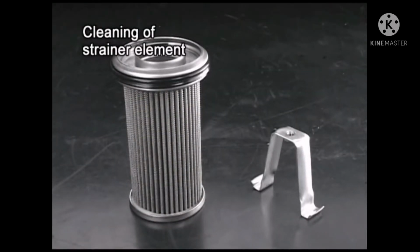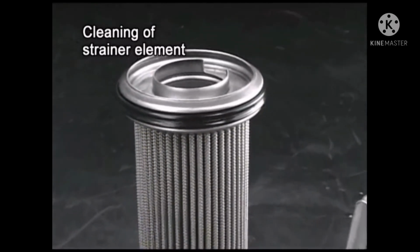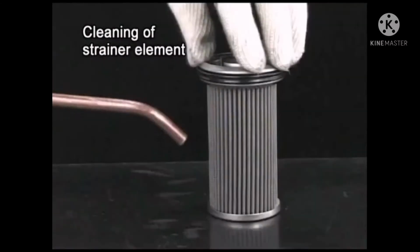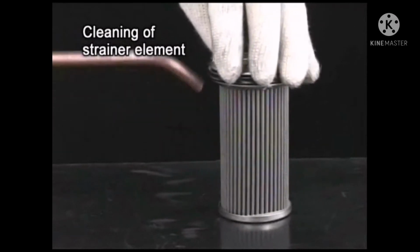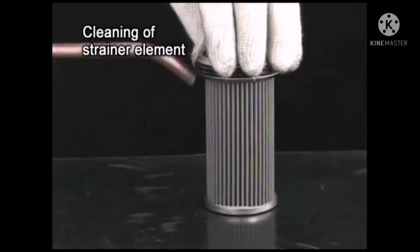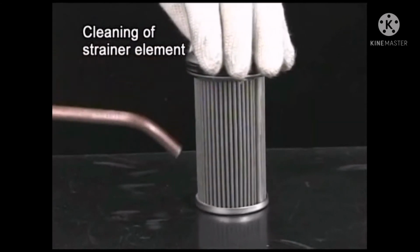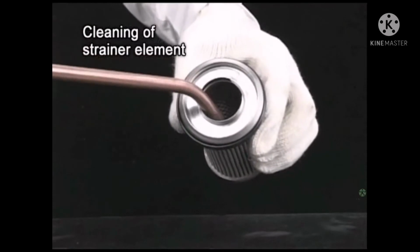Chemically clean the extracted element using a surfactant or cleaning agent. Blow compressed air from the inside of the element. It is more effective to use hot water of high pressure instead of compressed air. Also check for surface scratches, breaking of wires, corrosion, and other notched wires.